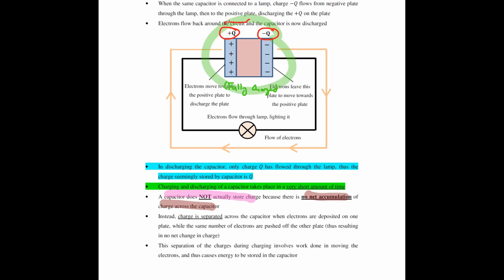But if you consider the capacitor as a whole, your net charge is positive Q plus negative Q, giving you 0. So there's actually no net charge here. That's the reason why we say your capacitor isn't really storing charge. If you were storing charge, you should have a net increase in charge.